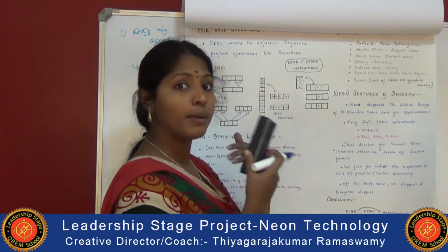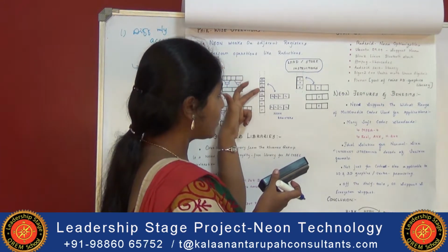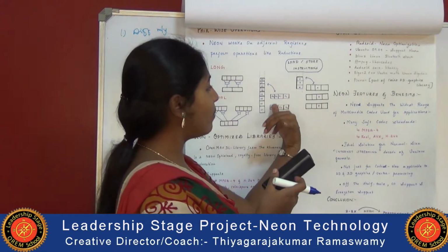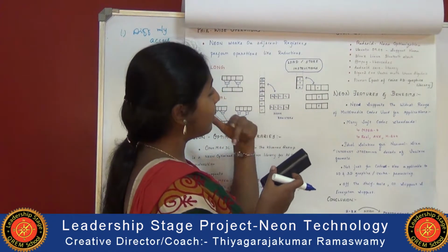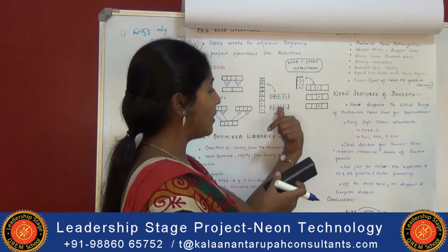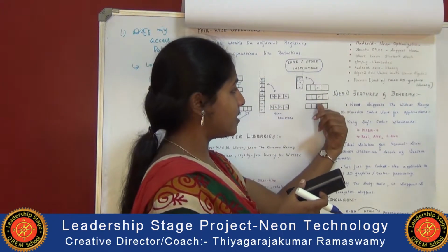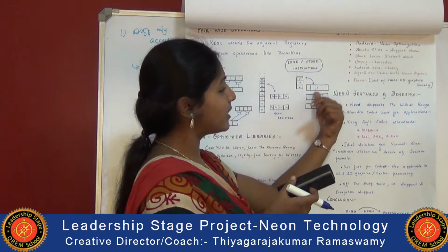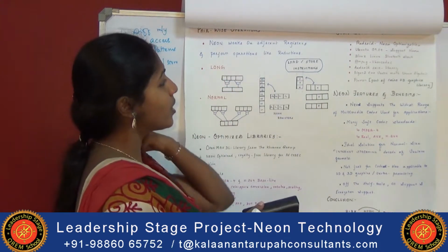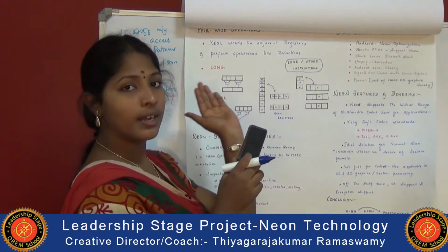How the different memory access patterns can be achieved over here: there are x0, x1, x2, and this is the allocation, and the memory access stored by this load or store instruction can be either x0, x1, x2, x3, and different permutations can be done over here in this NEON register. In the same way for the x, y, z, it can be like x, y, z, or the same thing, or different permutations are possible here also. So that covers the load or store instructions and the pairwise operations done in NEON.